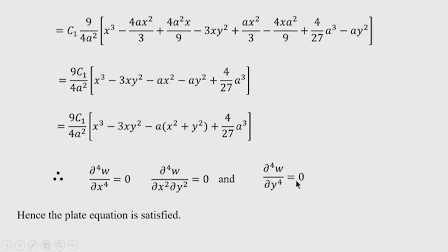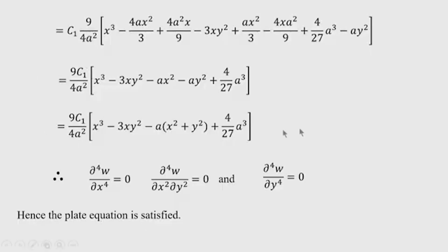So, the differential equation is also satisfied, because we have found del 4 w equal to 0 in that case, because no distributed loading is there, no applied loading is there except the edge moment. So, q is 0. Therefore, the differential equation is a homogeneous equation, and by taking the expression of the deflected series with this form, it is easily verified that the differential equation is satisfied. So, the plate equation is satisfied, that is our inference.